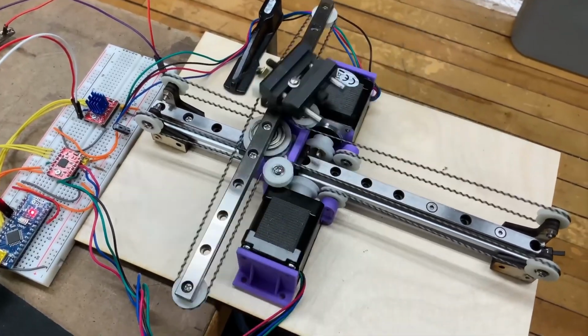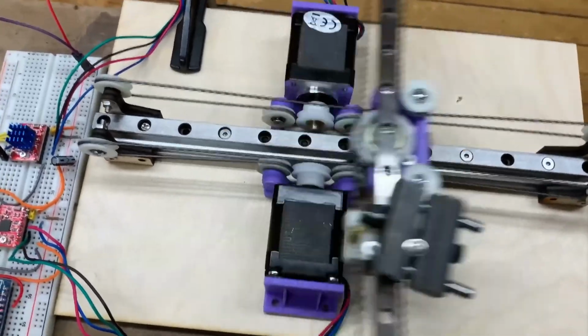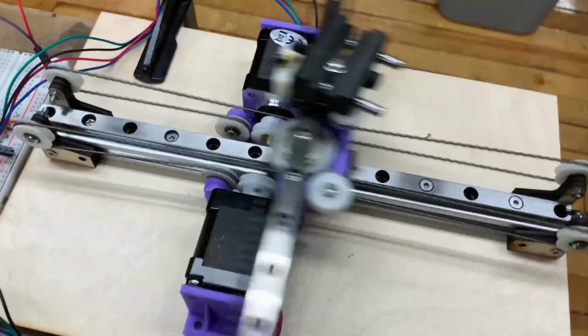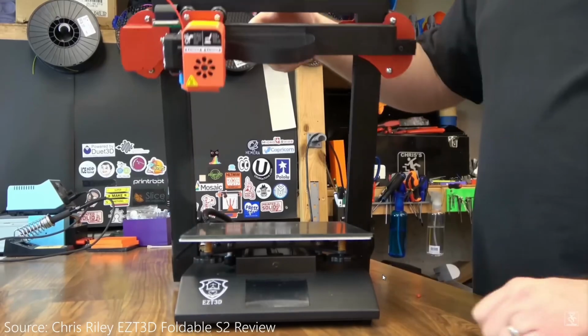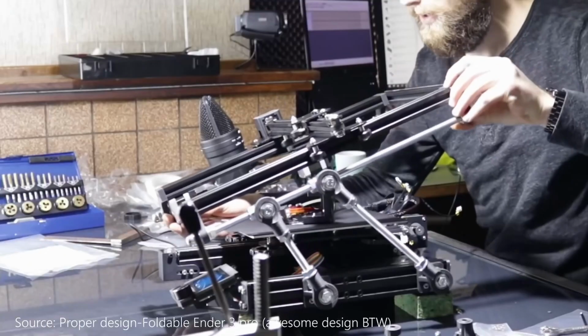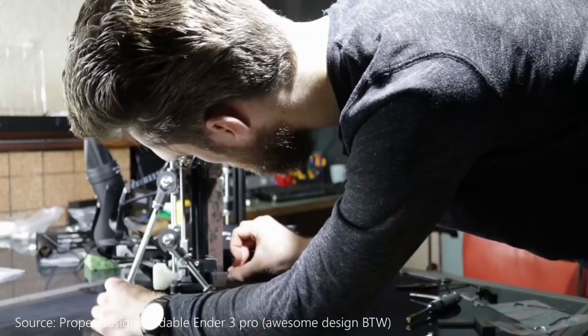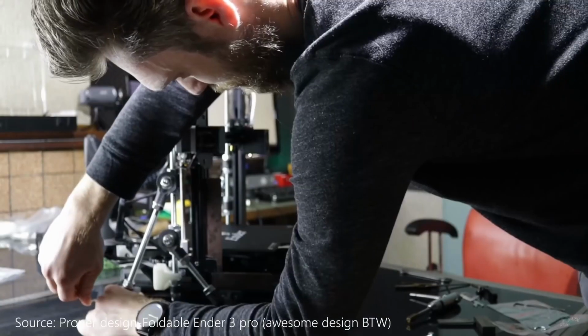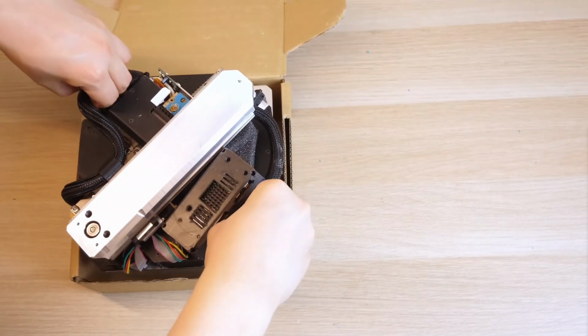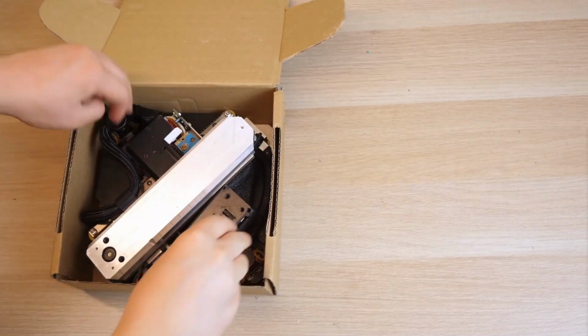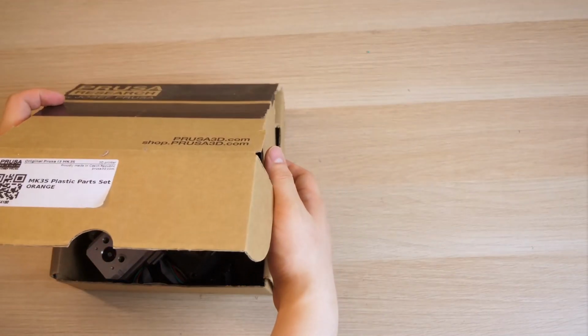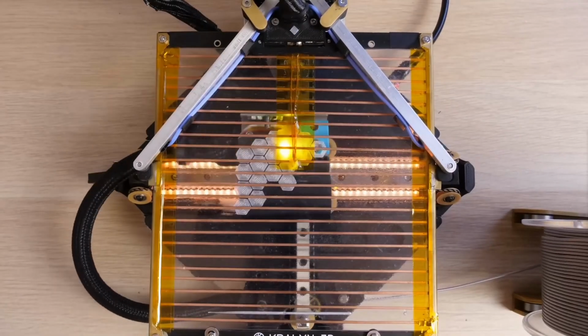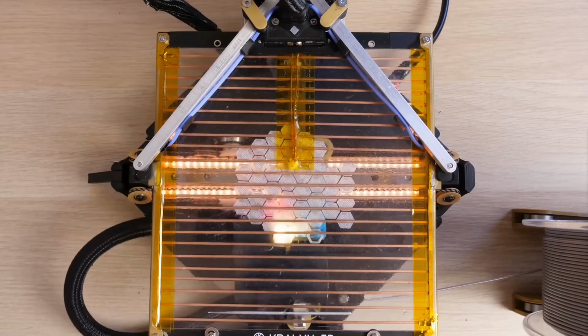Another benefit of this upside down structure is that now the X and Y axes are both on the same plane. Most foldable 3D printer designs fold down the X and Z axis, which can make the printer realignment quite tricky. However, in the case of the Positron, the X and Y axes are never folded, meaning that the gantry will always remain square and perpendicular.